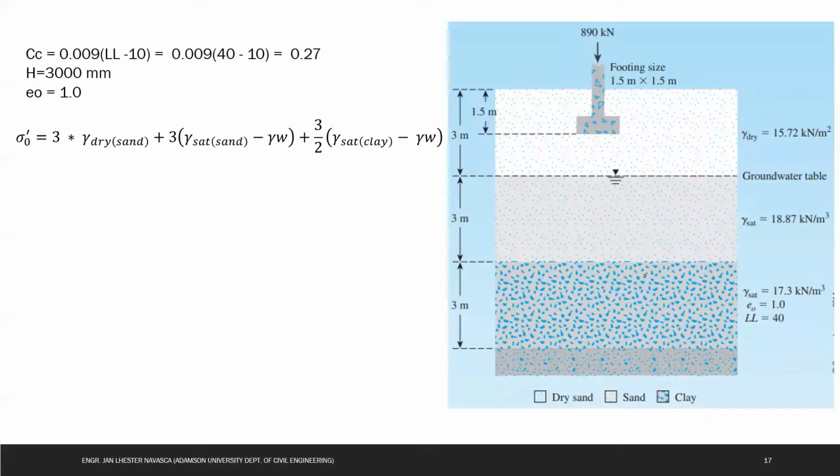So since we have this set up, how to solve for the effective stress? Just simply take the effective stress at the middle of the clay layer.